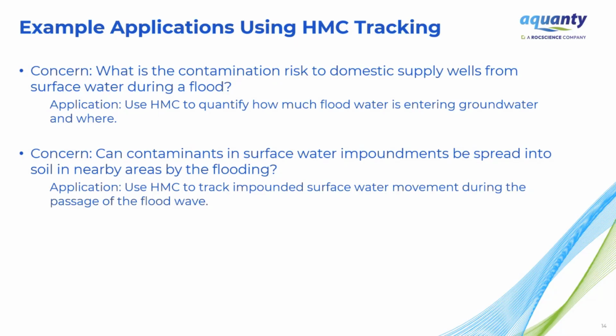If a municipality or city is drawing water from its alluvial aquifer, the concern for contamination is quite high during a flood, because the flood wave tends to pick up a lot of contaminants. It can be things like bacteria, so flooding of, say, agricultural lands, and carry that into the vicinity of the aquifer itself.